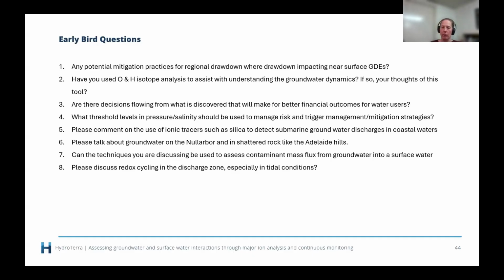I know it can be key areas of groundwater recharge. Main thing I'd say with fractured rock is it can be really difficult to assess and characterize flow paths and connections. And the variability in fracturing and the fracture orientation can be quite key.